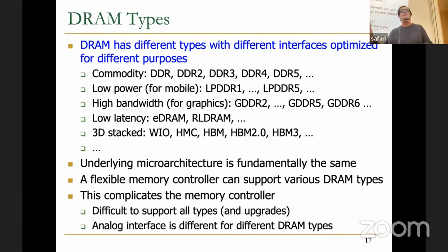So one way of thinking about the memory controller is taking it to a separate chip. This used to be the case, as we mentioned, 18 years ago or so. And AMD was the first one to bring the memory controller onto the processor chip. And then Intel followed suit because that was the right thing to do. With VLSI integration, you have a lot of logic to use, clearly. And bringing the memory controller to the processor chip was a good idea because it cut the latency, right? It's much better than scheduling requests to a separate memory controller chip, and then that memory controller chip scheduling requests to a DRAM chip, or DRAM module.